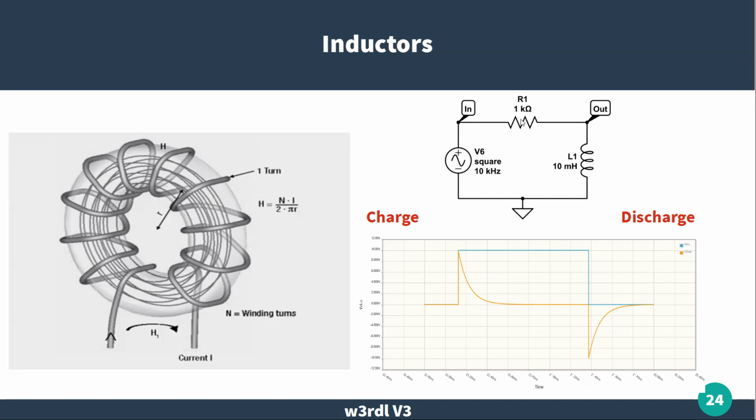So I did the same kind of circuit with the limiting resistor, applied a voltage to it. And you can see that initially it appeared to be 10 volts, because it is initially resisting current flow to that step function. As the current flows and it charges up the magnetic field, the voltage that we see across it, opposing the current flow, decreases. And again, you've got a time constant thing. And out here, it's essentially a short circuit, or just the resistance of the wire itself.